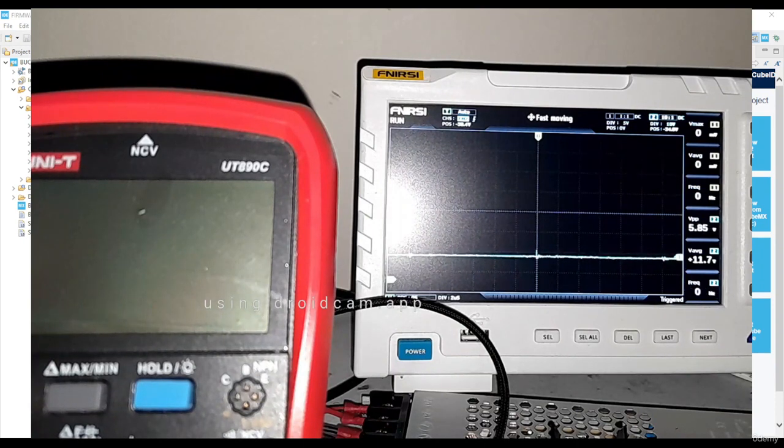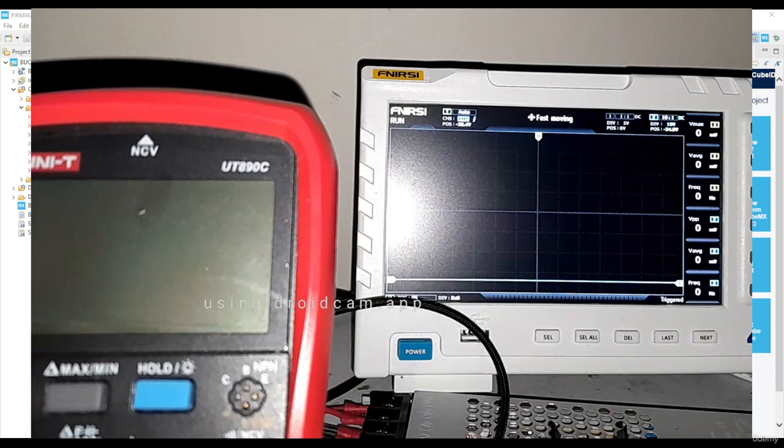If you want it to be a lot smoother, you'd have to change the coefficients to align with it. But if we actually take a look at the inductor current, which unfortunately cannot be done in this case because there isn't a current probe, one will actually find out that it's continuous. It's in CCM, which is fantastic. I'm just gonna keep saying it's fantastic. But now I'm literally gonna change the set point in the code to a different value.